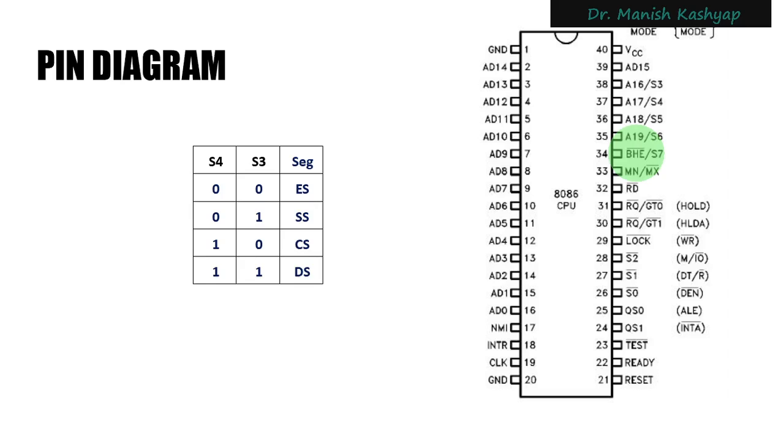Now the addresses that you have in the external memory will be in 20 bits. So you will have an address of five zeros, then 00001, 00002, and so on in hexadecimal, right?